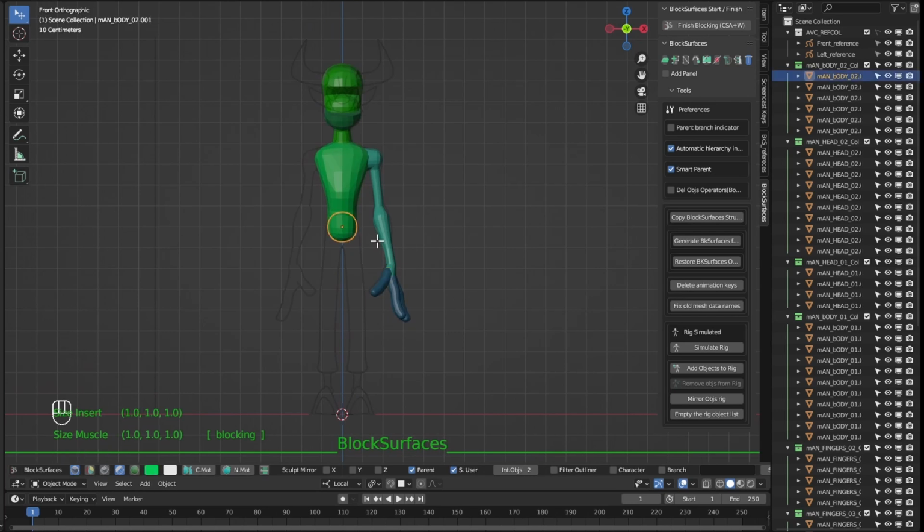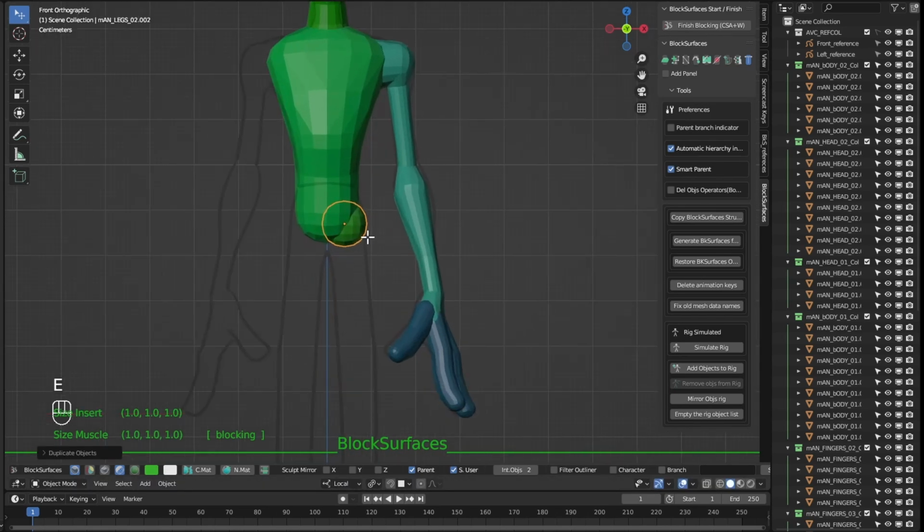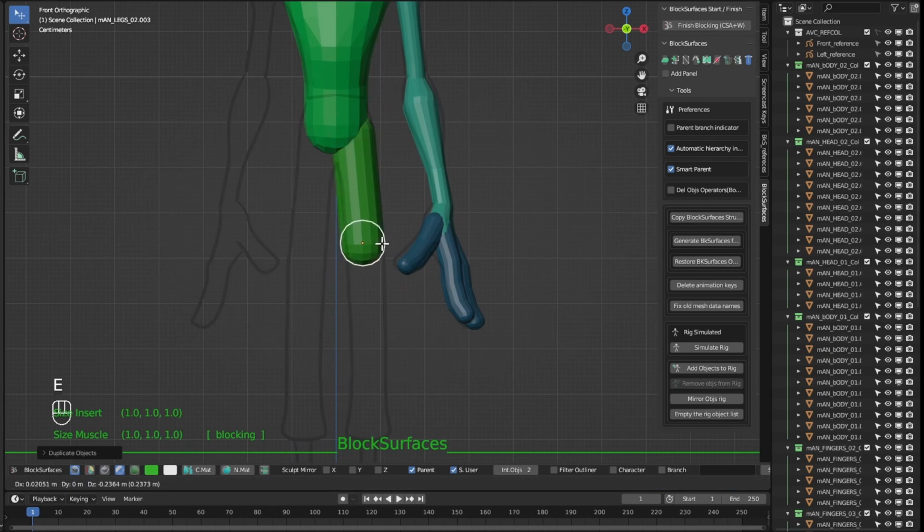Okay, let's continue with the character, and in the same way, let's create the legs. Then, once again, we create the new branch with a trunk object selected, Ctrl+N, and extrude with the shortcut E, and go looking for the shapes of the different views.